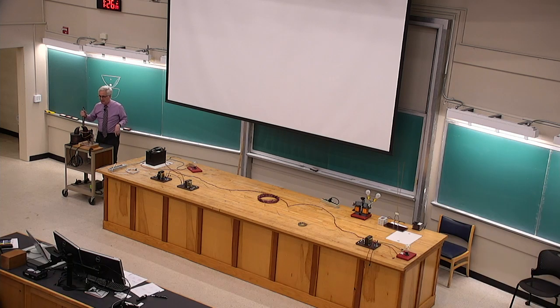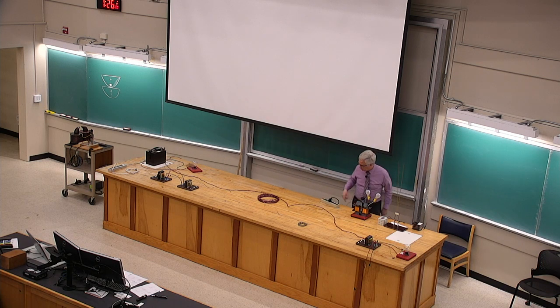Is it okay? It's a complicated story, and I realize it's hard to pass along with words. But that's what's happening when I turn on just the coil. The current first builds up a magnetic field, then builds it down, then builds up the magnetic field the other way, because the alternating current really does reverse. So energy is going into the magnetic field of this piece of iron, and then it's coming back out. Going in, coming back out.